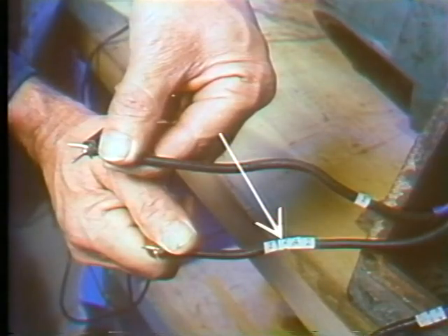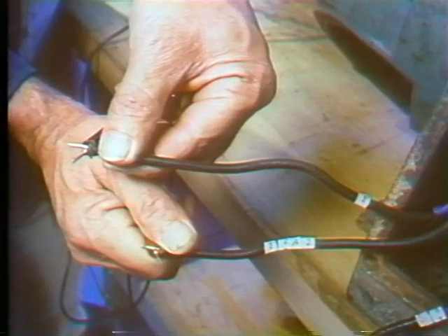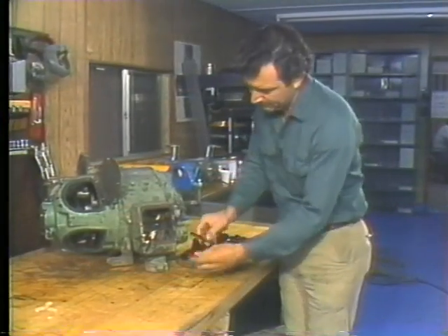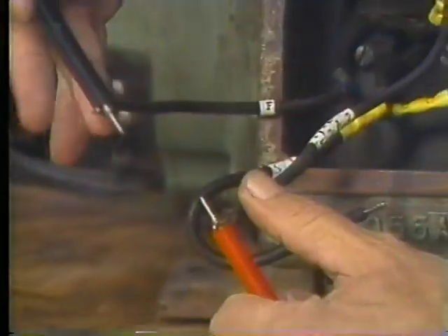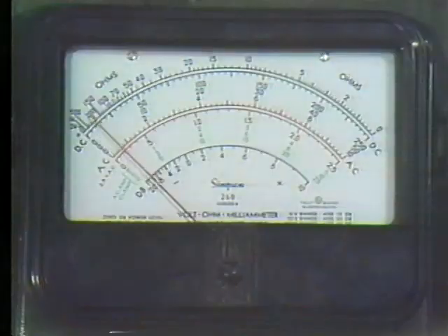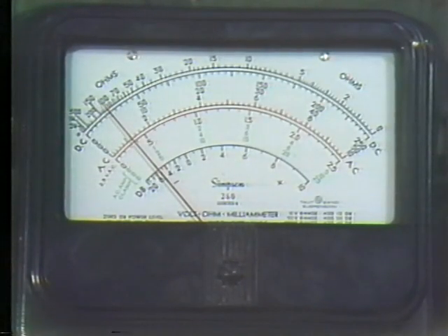But it's got A2 on it. That would be a problem if we hadn't lifted the brushes off the commutator. But since we did, we took out the armature circuit. So we can be sure we're reading only the shunt field. Okay? With 1 ohmmeter lead on the shunt field lead, F1, and the other on the shunt field lead, F2, we should get a reading. And we do. That means the shunt field's not open.